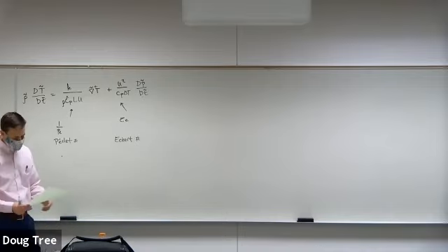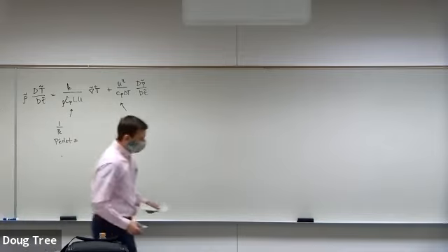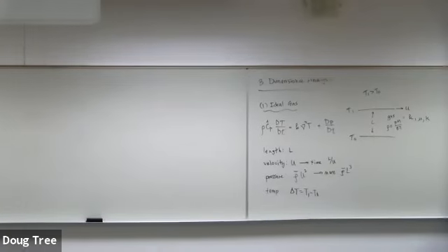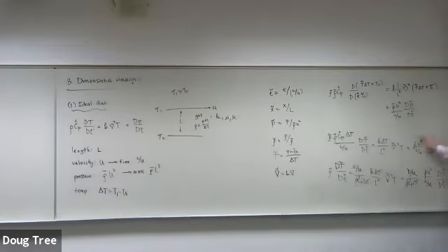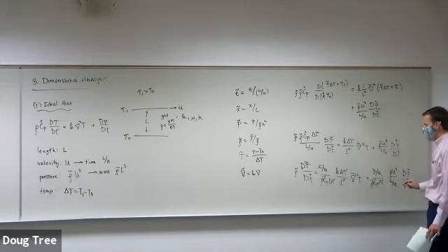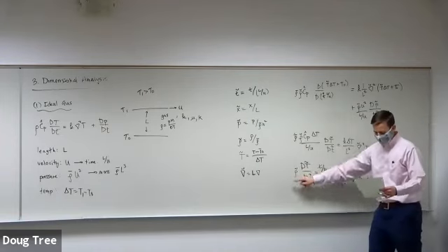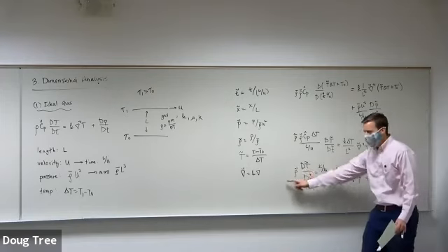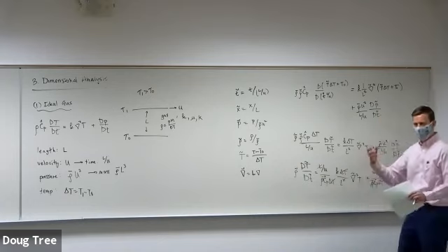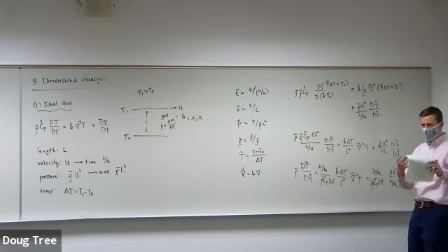The Eckert number is a ratio between, we can go back and look here. Well, this is inertia, right? This is rho u squared. So this is telling us inertial stuff. And then we divide it by the stuff over here, which had to do with the enthalpy. So what this is really telling us is a kinetic energy ratio versus enthalpy.